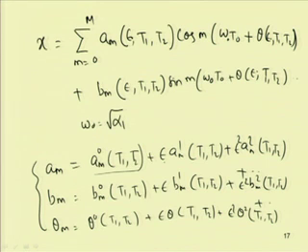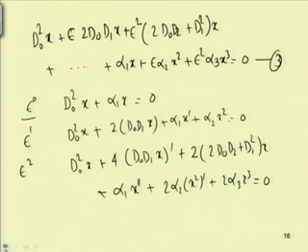Also, in the case of the harmonic balance method, these terms Am and Bm we have considered as constants. So, in this intrinsic harmonic balance method, we are taking x to be Am, which is a function of T1, T2, that is scaling parameters, and also the bookkeeping parameter. Similarly, Bm also contains epsilon and the scaling terms, and theta also contains similarly. So, by substituting this x in the previous equation, that is order of epsilon to the power 0 and higher order, we can write this equation in this form.